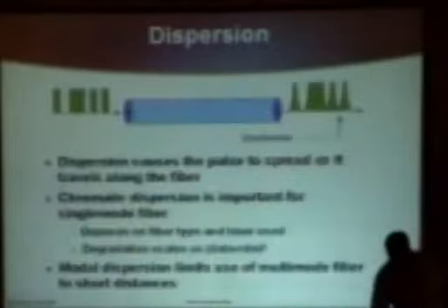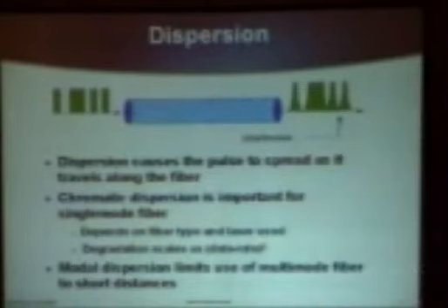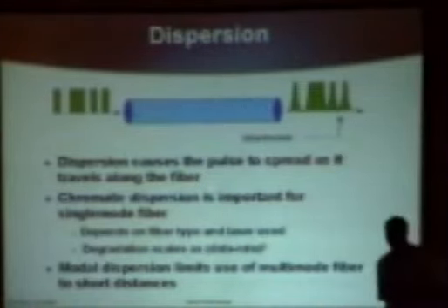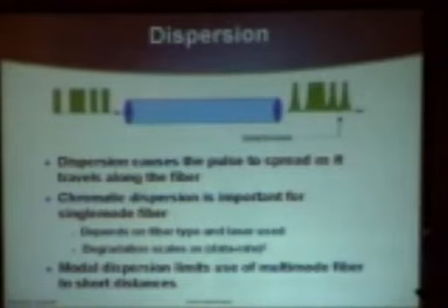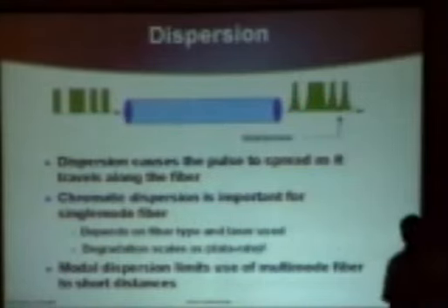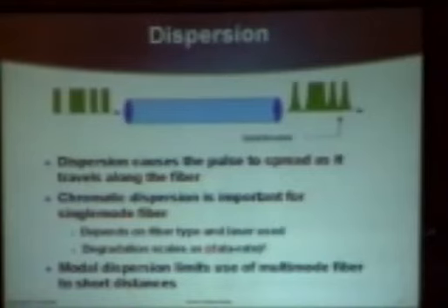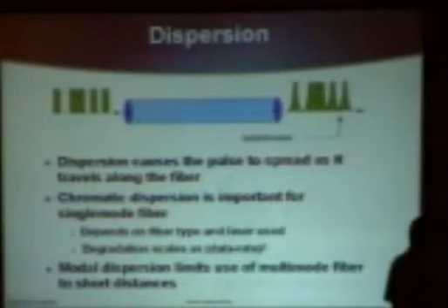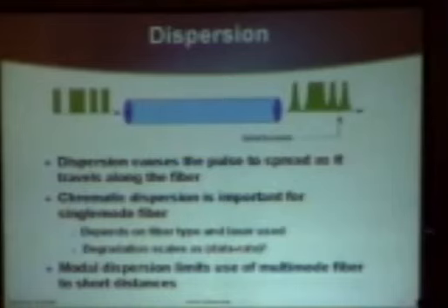So what does this all mean? It's all wonderful, but what it means at the end of the day is that there is a phenomenon called dispersion that happens in the analog transmission of ones and zeros over fiber. You put in nice clean shapes, and at the end of the fiber, you get muck out. And it's frequency dependent. This problem goes up like the square of the bit rate. So for slow speeds, at least in backbone slow speeds, OC3s, OC12s, and for the most part OC48s, dispersion isn't a great issue. But at OC192, where our backbones are going now, suddenly this dispersion problem becomes quite important.